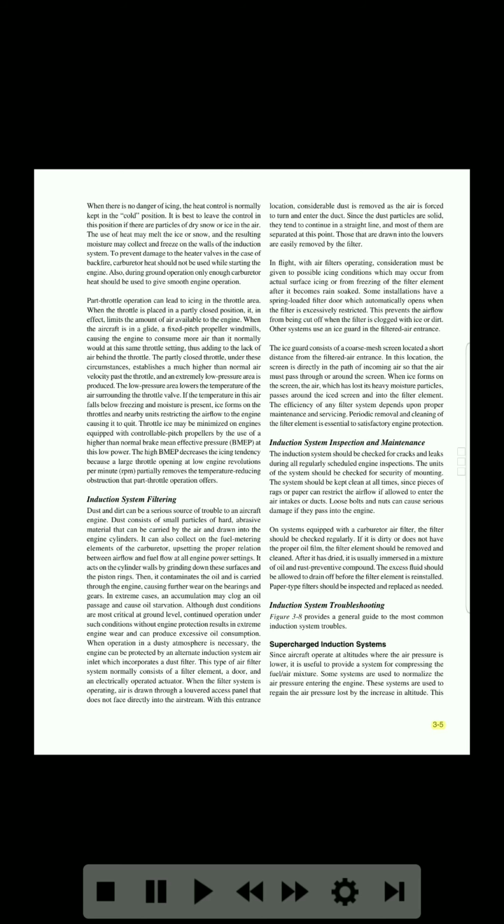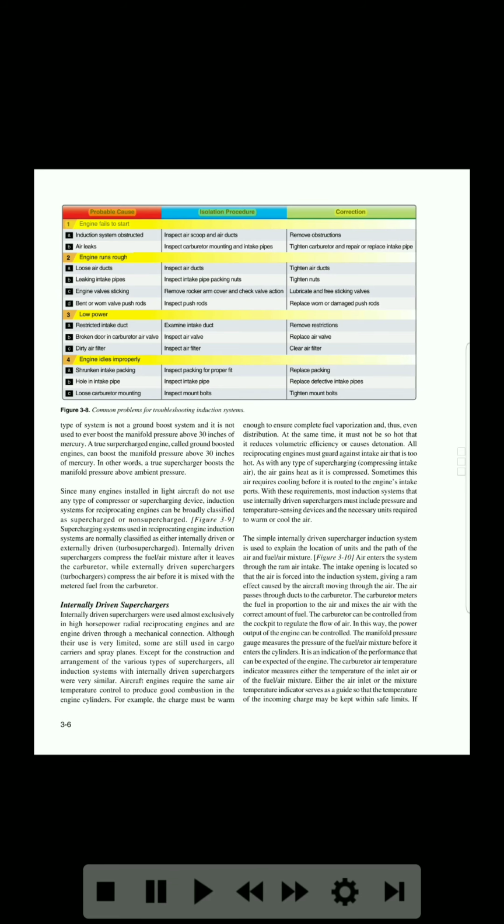Table 3-5. Probable cause, isolation procedure, correction. 1. Engine fails to start. A. Induction system obstructed. B. Air leaks. 2. Engine runs rough. A. Loose air duct. B. Leaking intake pipe. C. Engine valves sticking. D.